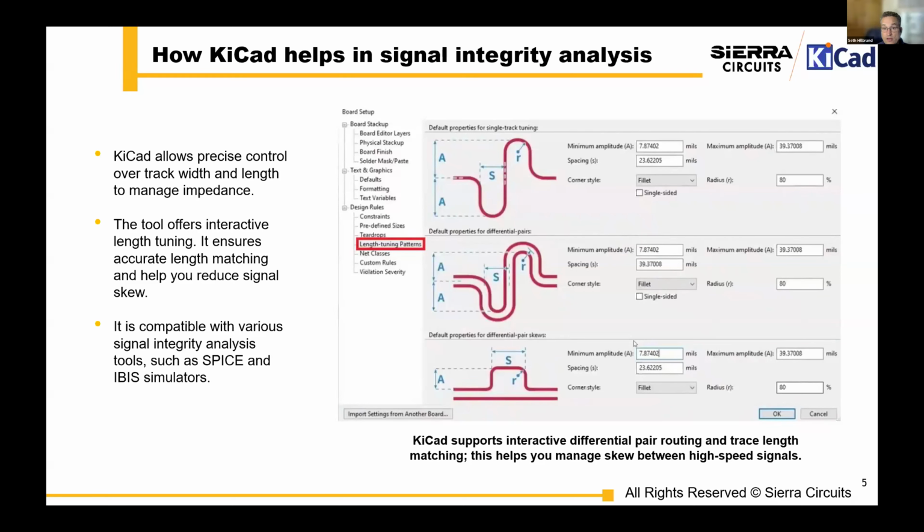Yes, without a doubt, you should definitely take advantage of length matching rule sets and skew matching rule sets in the custom rules. If you're dealing with differential pairs, you can set all of these constraints based on net classes, based on groups of signals, net names. All of these elements are controllable in your custom rules and definitely should be addressed there before you start designing. That would be the other key thing.